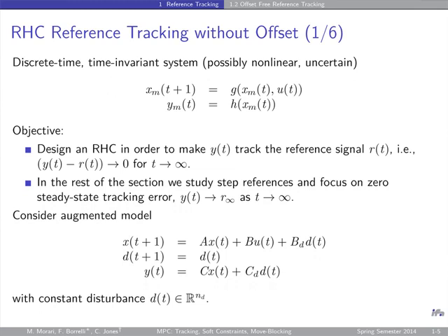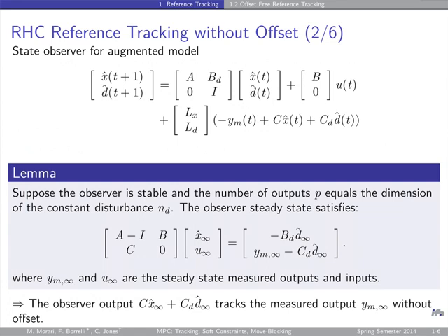The first simple thing you say is, okay, forget about this. I choose BD equal to 0, and CD I just choose identity, because I need the same number of disturbances as outputs, so I may as well choose identity. Okay, that's one idea. Looking back at slide 6, it says the following: choose CD equal to identity. What do you need for observer design? As I mentioned to you, for the Riccati equation to converge, this system here must be observable.